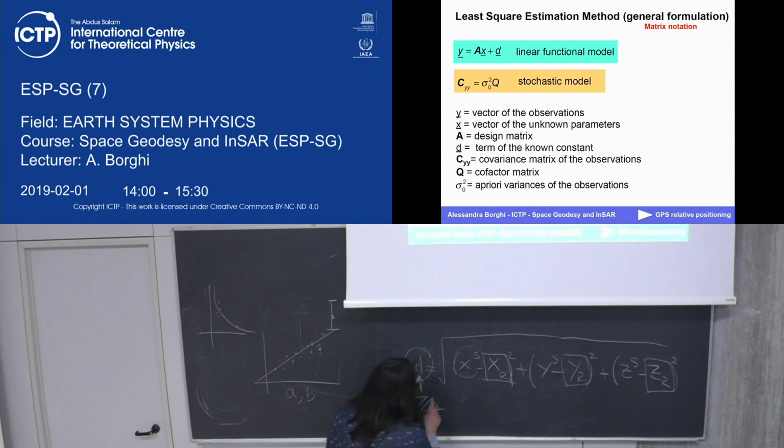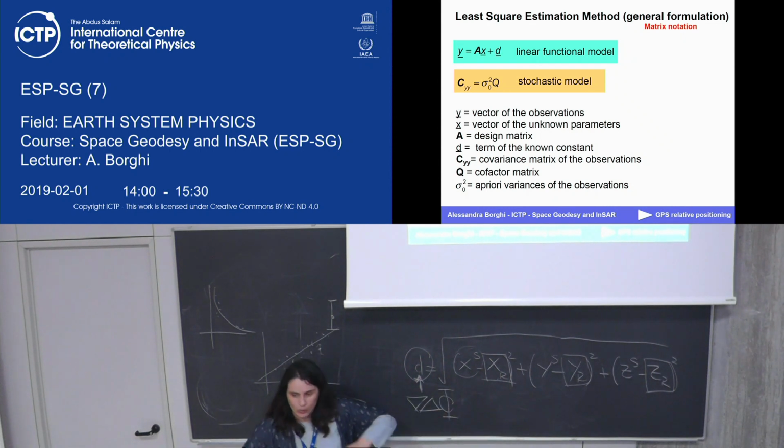We have our observations in terms of double differences, and we want to estimate, for instance, just the geometric parameters. We have a huge quantity of data because with GPS, especially for a permanent station or in a static survey, where I put my GPS on a monument and wait for an hour before I switch off the instrument, I can collect data every given second. I decide how many seconds.